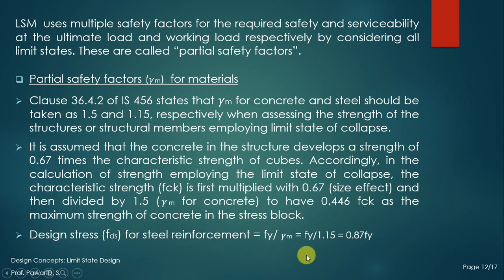Design stress for steel: Fy, that is the yield stress of the steel, divided by gamma m, so Fy divided by 1.15. So we are going to use the strength as 0.87 Fy in the design stress block.